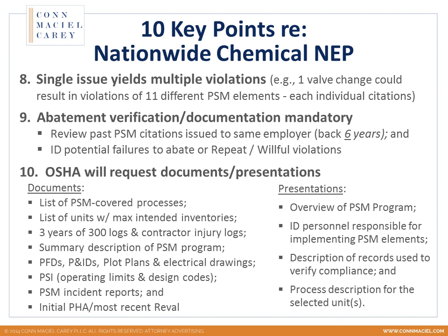They're looking back 6 years to find any past PSM citations, and part of their directive is that they must evaluate those past issues to see whether you've corrected them and maintained a correction of those issues. Are you operating, have you fallen back, or did you never correct those issues? So that's one of the things you can know, that if you've ever had a past PSM violation and OSHA's there under this NEP, they will be reevaluating the status of compliance with that issue.